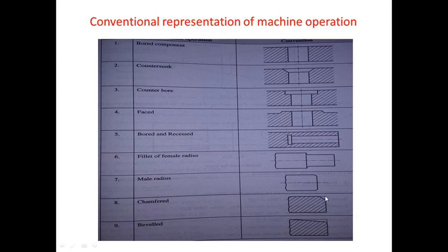So, you can see here, this was the sharp edge passing through the corner. This was my original workpiece and this was the corner. In order to remove this corner, the face or the edge is cut by some angle, basically 45 degree or 30 degree, and then the upper part is removed. So, we get a surface that does not contain any sharp edges. So chamfering is basically done to remove sharp edges so as to prevent injury as well as to distribute the stresses.